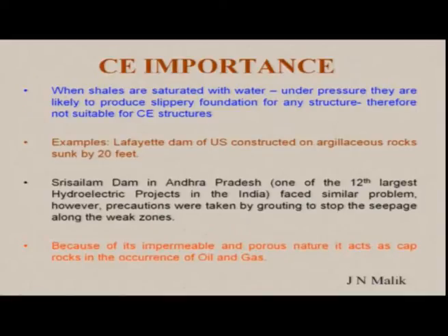Then, because of its impermeable and porous nature, shale acts as a cap rock for the occurrence of oil and gas. So, in a way it is good for the fuel minerals, but it is not good for foundations.